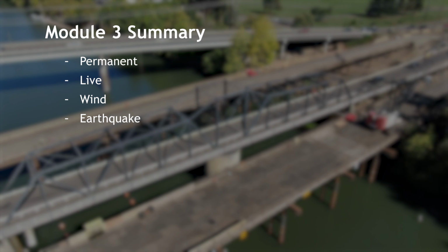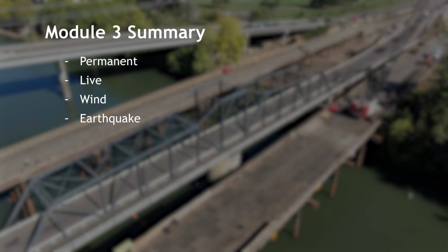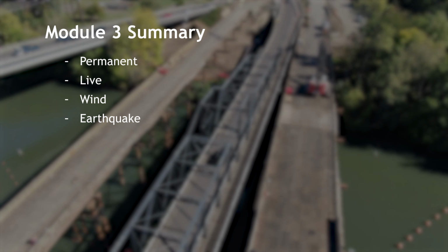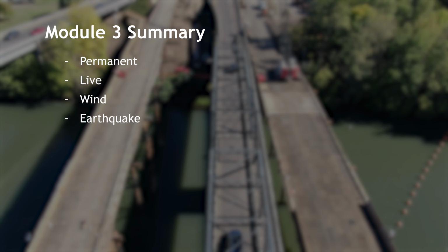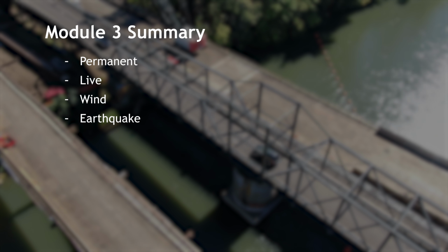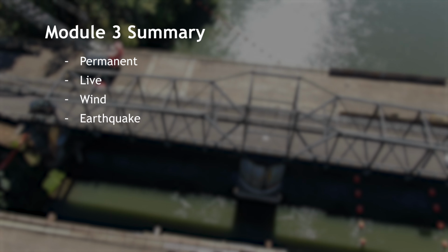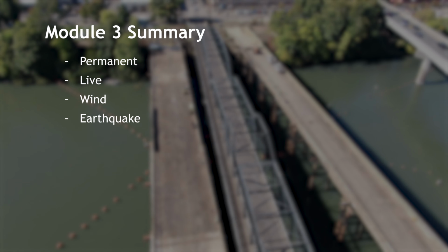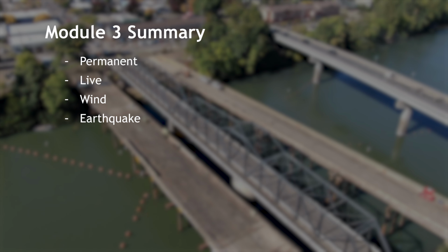In this video, we have introduced the fundamental loads which occur in bridges and focused on permanent, live, wind, and earthquake loading. The AASHTO LRFD bridge design specifications greatly expands on these and other loads and provides extensive guidance on how to apply them. With this information, you now have the basics of bridge loading that will input into every aspect of your structural designs. In the next modules, we will use these to analyze trusses and beams and input them into finite element software and seismic design.